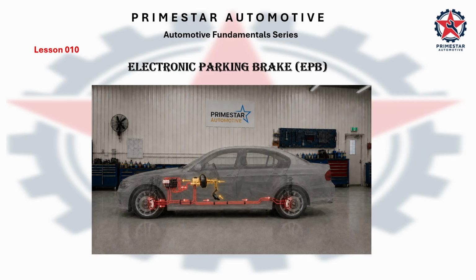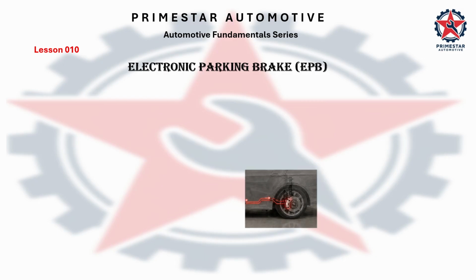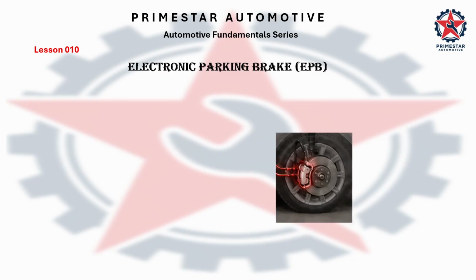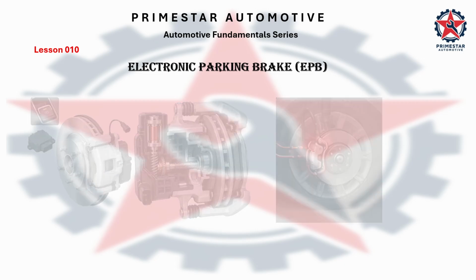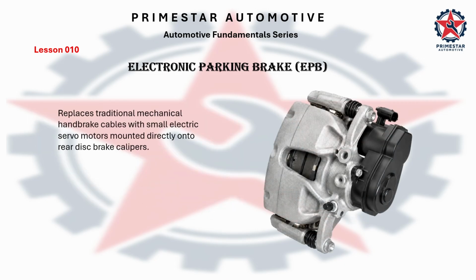Electronic Parking Brake, or EPB. EPB replaces traditional mechanical handbrake cables with small electric servo motors mounted directly onto the rear disc brake caliper.